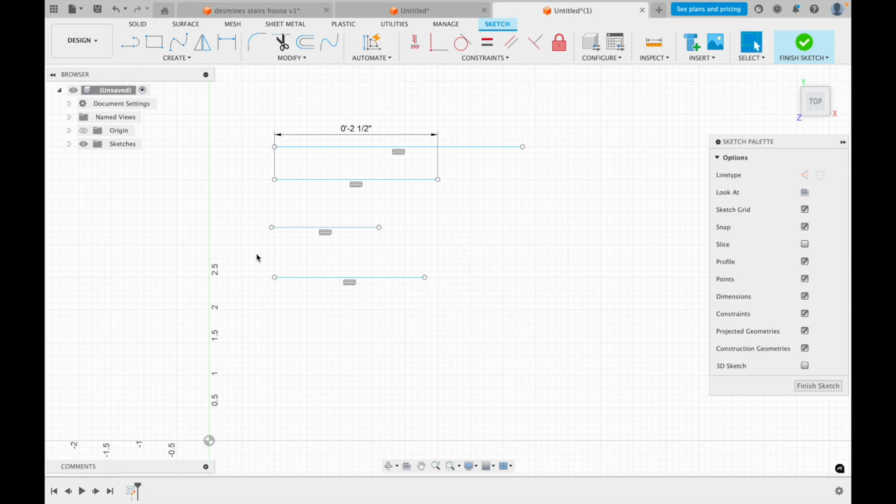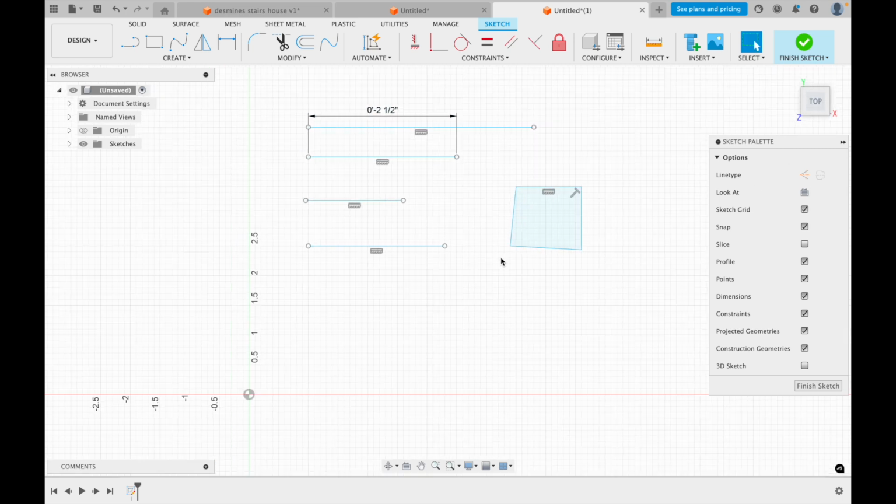Okay. So these are the standard lines. These are what you're going to use to make a square, for example, or your piece, right? The other line type is called a construction line. So press the L or click this. And then before you click on the line, you press either the X or this button right here. It says construction. So you click that, and now it gives you a construction line, or like a reference line, for example.